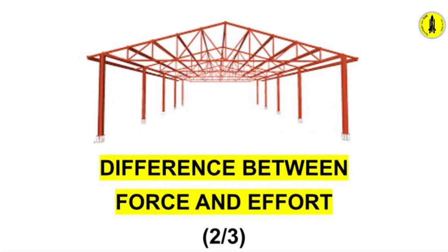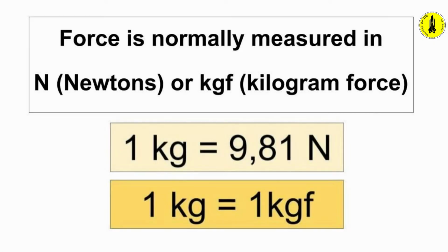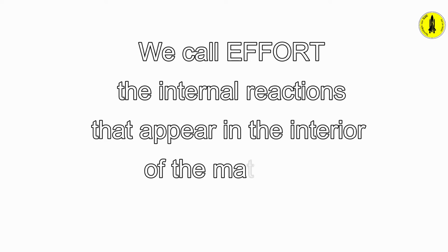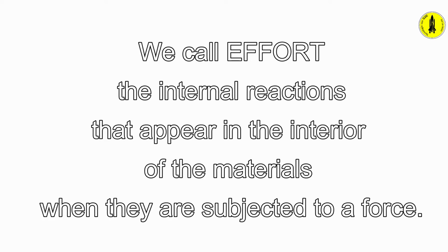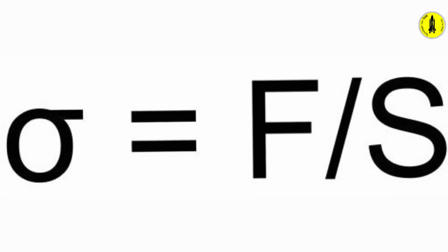The difference between force and effort. We call force anything that tries to break, deform, or displace a structure. Force is normally measured in newtons or kilogram force. We call effort the internal reactions that appear in the interior of materials when they are subjected to a force. To calculate effort, we divide the force by the area.